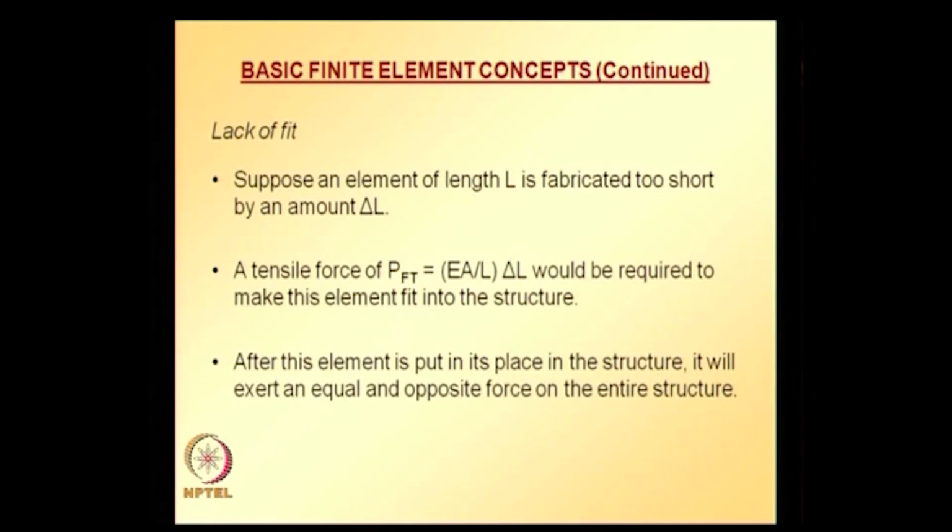When you force fit, the member will be under compression, and in turn that member will exert an equal and opposite force, which is going to be a tensile force if it is too long. Since the member that is too short will be under tensile force, it is going to exert a compressive force on the structure.